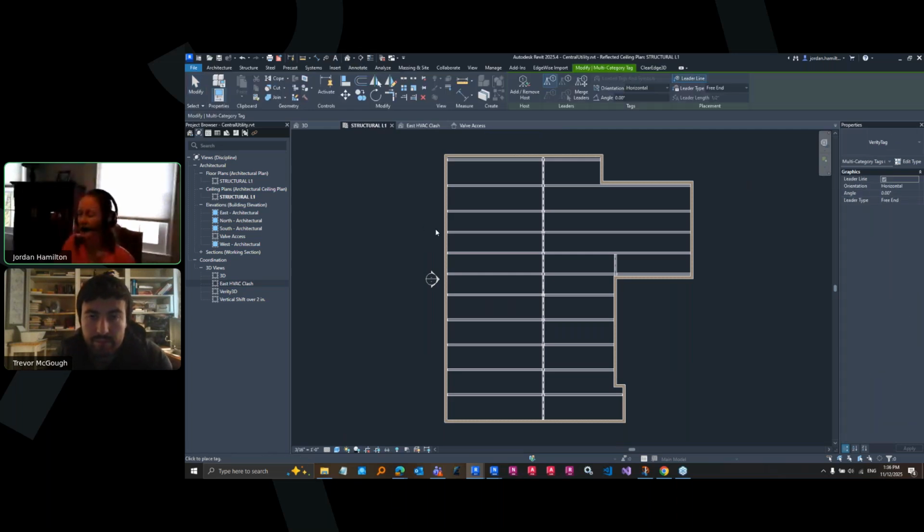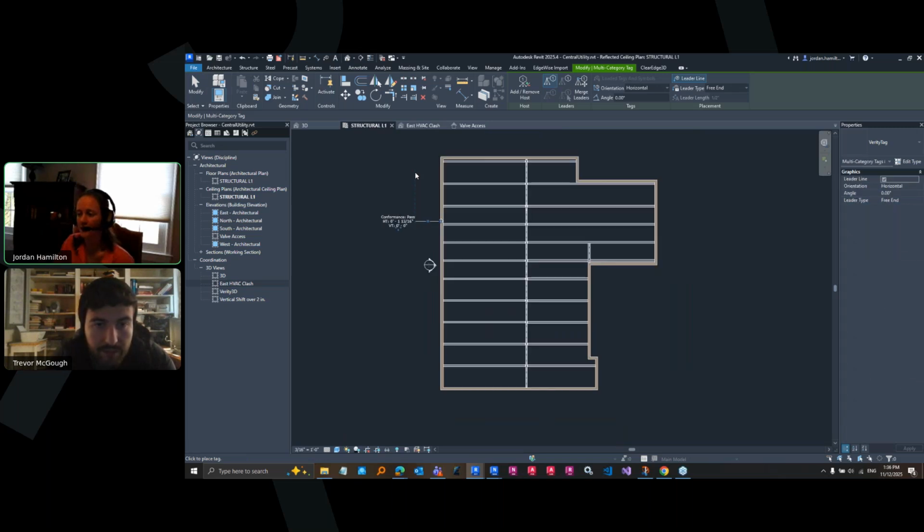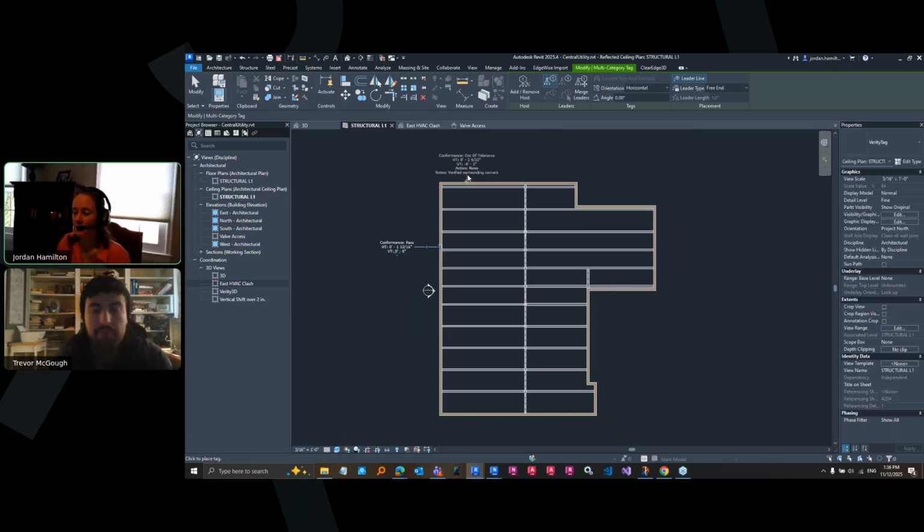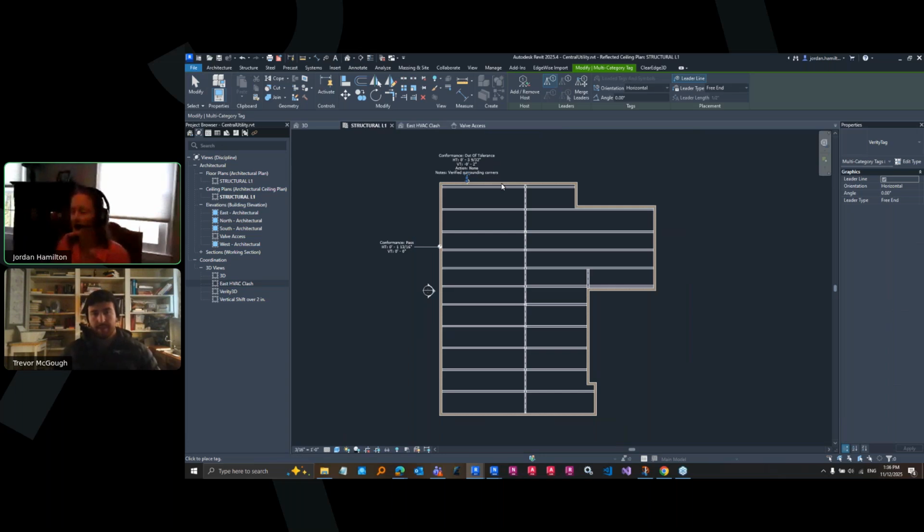on your needs. I have a very simple tag set up here that's going to show me my conformance to tolerance, the horizontal translation and the vertical translation. I can also have it show any notes or action required from the Verity analysis. So having these Verity properties available even to use in annotation tags makes setting up a reporting view very, very simple.